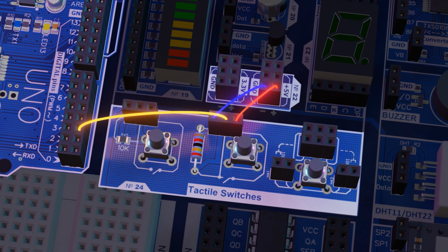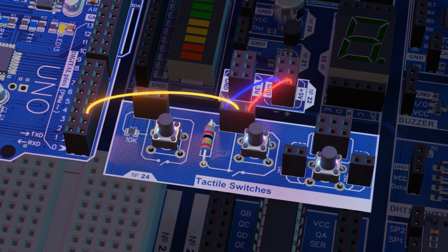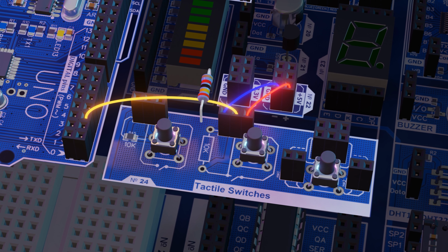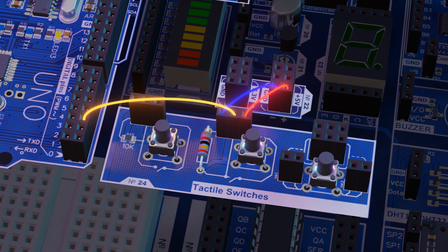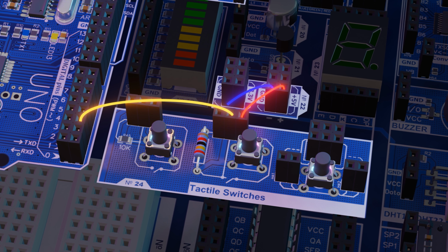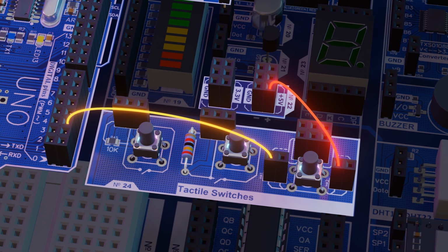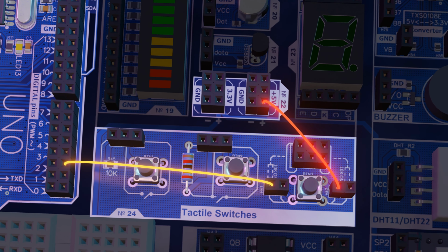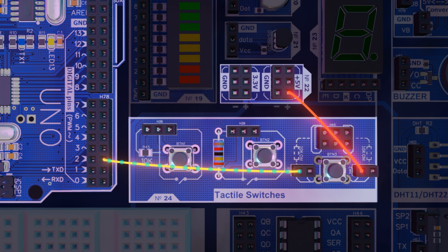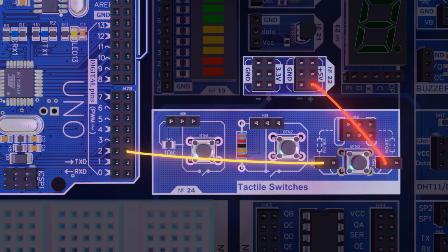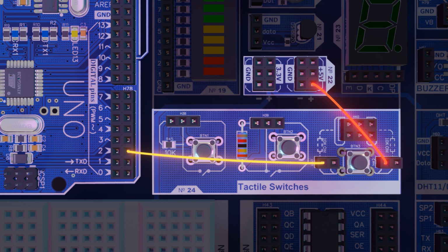Here you might have a reasonable question. Why did we also ground the button through a 10 kilo ohm resistor? To answer this, you can imagine that we connected the button without any additional resistors. Here, between pin number 2 and ground, there is a small capacitor. It is capable of accumulating charge. Many microcontrollers have this feature.